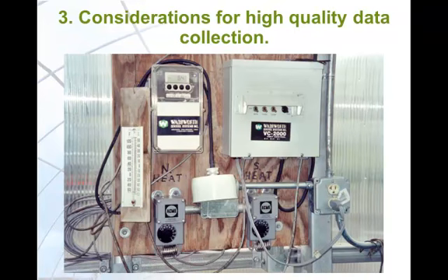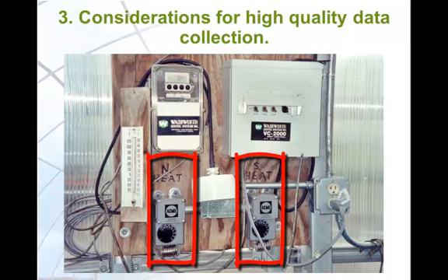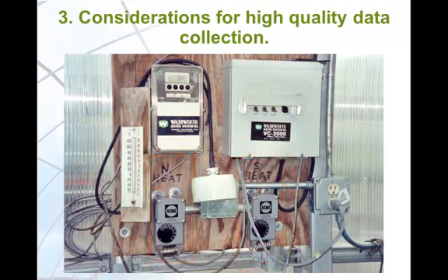Here we have a picture of two separate heat systems, north heat and south heat, controlled by thermostats side by side. This system could be improved if each thermostat was moved to a location representative of the heater it controlled.